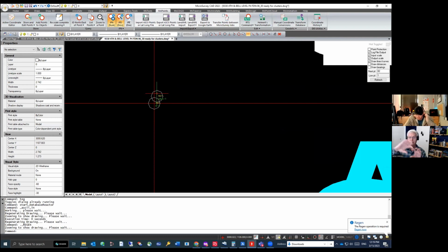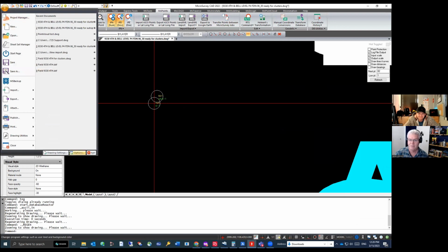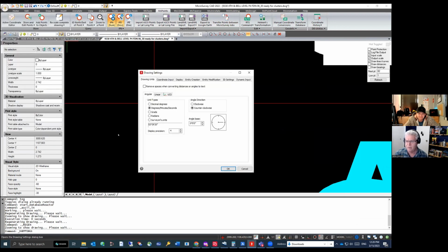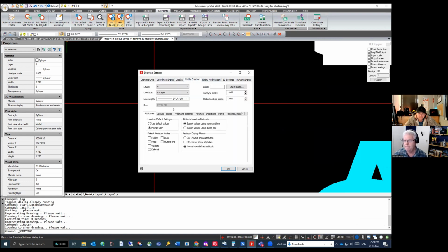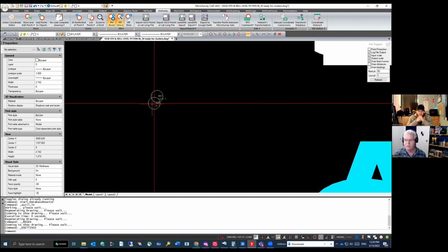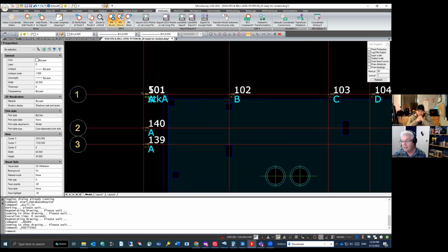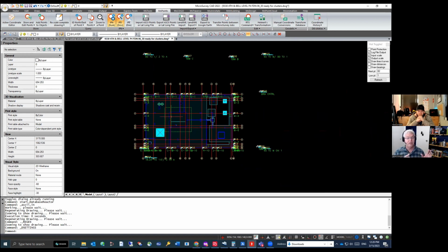You'll notice I'm showing the point nodes as, here, let me do a quick regen so they show as circles. What I've done here is something similar to what Mack likes to do, which is play around with how point nodes are displayed by drawing them as circles, and those circles are 0.1 unit in diameter. So we get an idea of how close those points are. If we zoom back here, if you know exactly where you're going, you could zoom in and see how close all your stake points are.